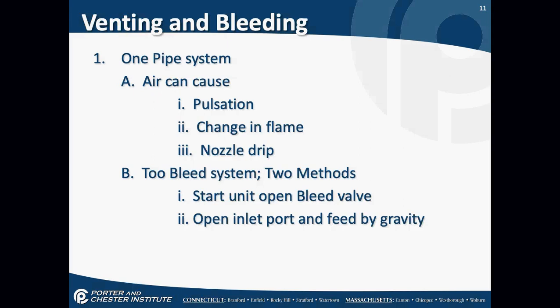Now, when we're looking at an oil line that's running across a basement, let me just do one of my lousy drawings again. I have an oil tank sitting here. It might be one side of my basement. I have the oil line coming out of the tank, might be going around the walls. It's usually enclosed in plastic, and it comes to my burner that's mounted on my furnace. Connects to a valve here. There's a whole valve assembly there. This line that goes across the basement cannot have any compression fittings in it.